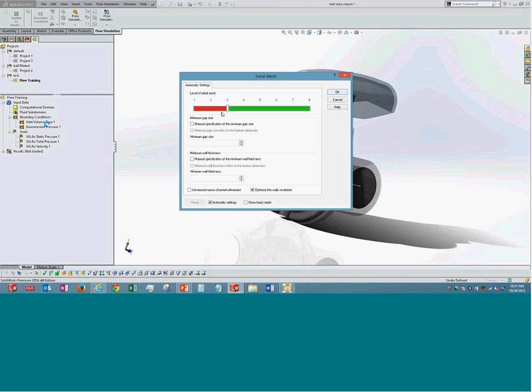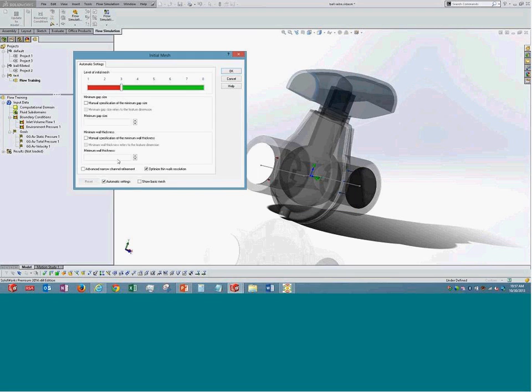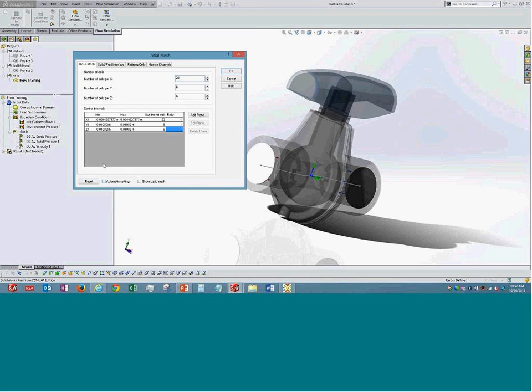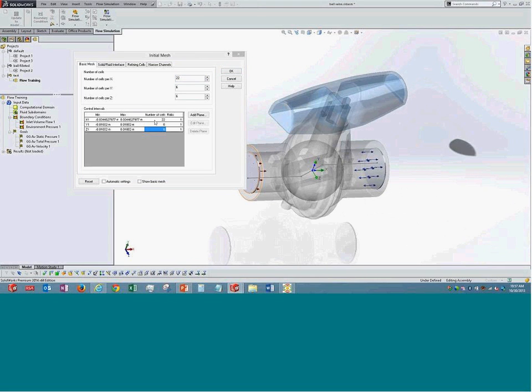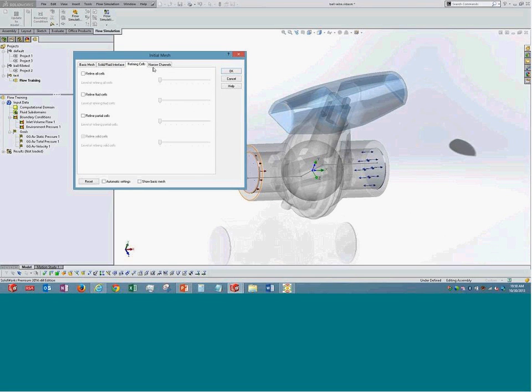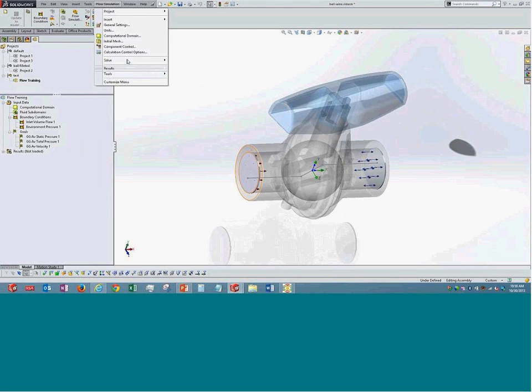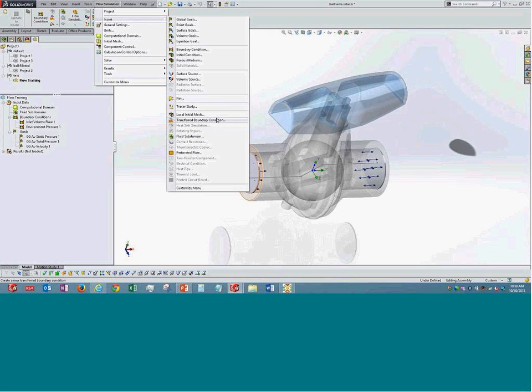You can see the initial mesh. Using this, I can specify a certain surface or a volume at which I want to refine the mesh. So we can create a junk geometry inside the system wherever I want to refine it, select it, and tell the software to refine the mesh at that location only to a very fine extent. In terms of visualization, if you want to see the mesh, it can be seen from multiple places. Right click on mesh over here and have a 3D view of the mesh.